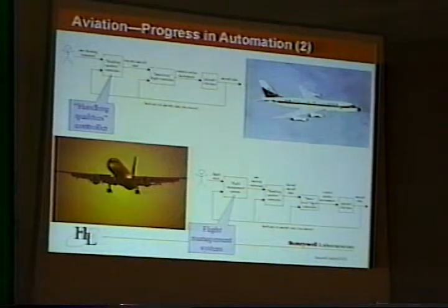All modern commercial aircraft have flight management systems, and all that a pilot needs to do is input a route. This route is input by way of identifying waypoints. So at what time do you want to be over what particular location at what particular altitude? That's all that the pilot needs to specify, and the automation takes over from there